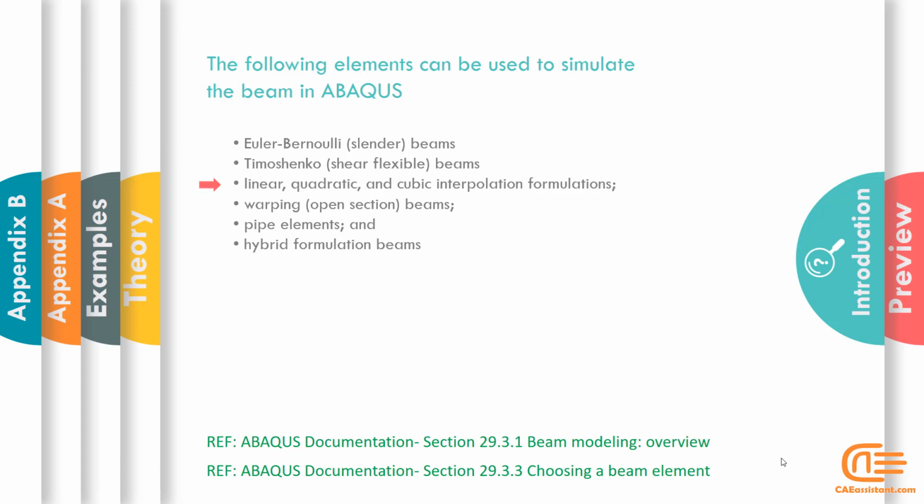Beam elements use quadratic and cubic interpolation functions, which makes them reasonably accurate for cases involving distributed loading along the beam. In the following training, I will talk more about this. When modeling a beam in space, a further consideration arises from the possible warping of the beam's cross-section under torsional loading. For all but circular sections, the beam's cross-section will deform out of its original plane when subject to torsion. This warping deformation will modify the shear strain distribution throughout the section.